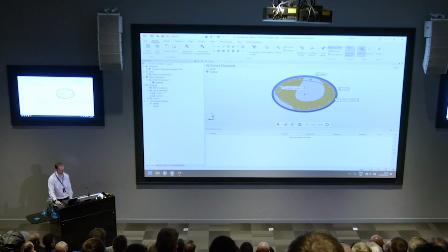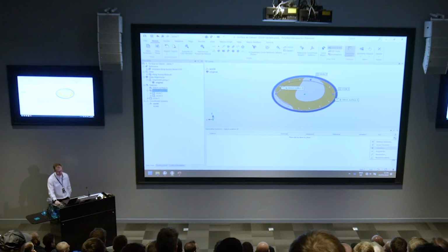Perfect, and then going back to the presentation, there was a call out of position, so I'm going to use this datum pattern here. So for example, I'm going to jump into datum pattern B. Within my geometry controls, I can add GD&T, and I can add position relative to now datum surface A. Okay, there is an error there, but this is all by design, just to show you how it works.